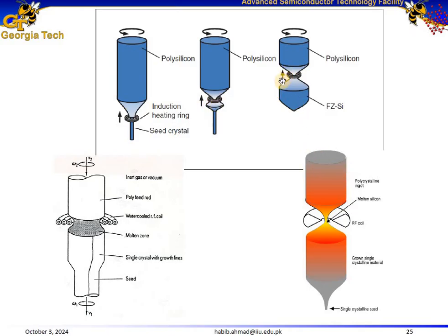So here you see a taper formation. After the necking process, the molten zone is gradually widened, as you can see, this tapered region, to increase the diameter, and this forms a taper. This taper allows the crystal to smoothly reach the desired diameter for the steady state growth, and the controlled taper ensures that the crystal growth transitions smoothly from the narrow neck to the desired diameter.